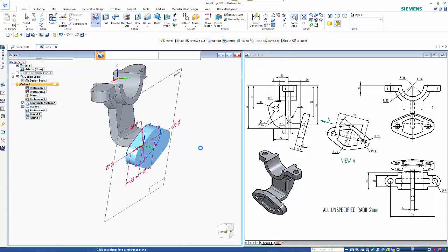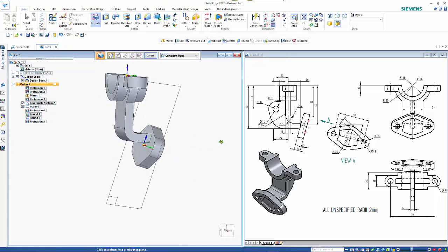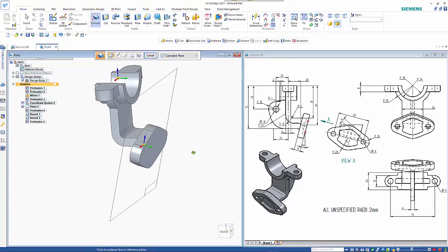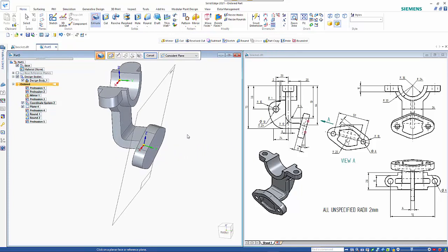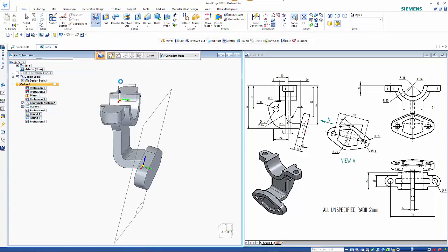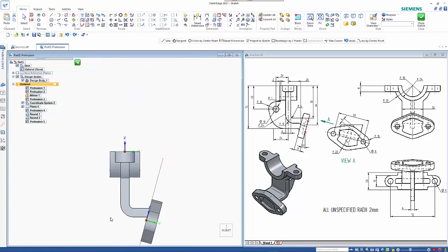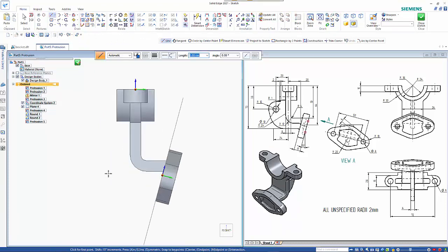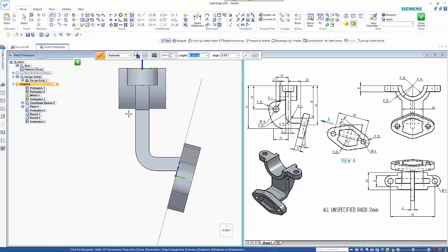So we're getting quickly into where we want to be. So the last extrusion I need to do is on this plane here. So I'm coming with the line command down, out, hit the A key for an arc, and it wants to be somewhere.